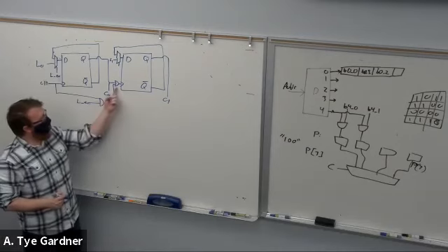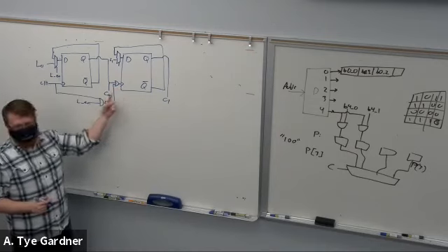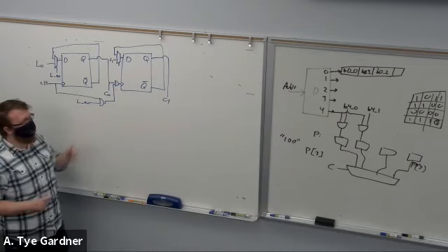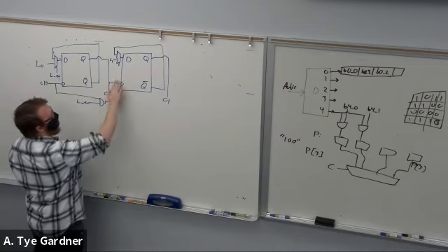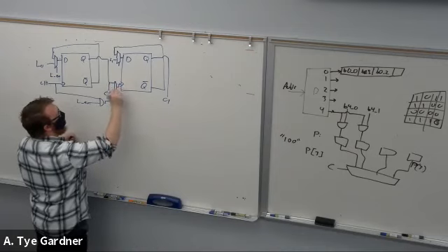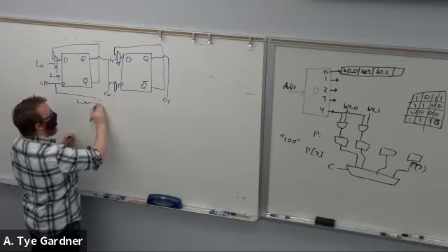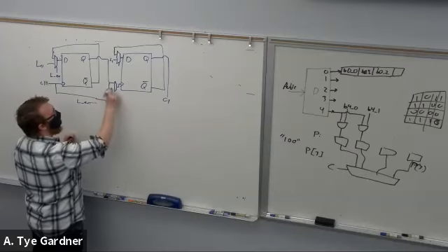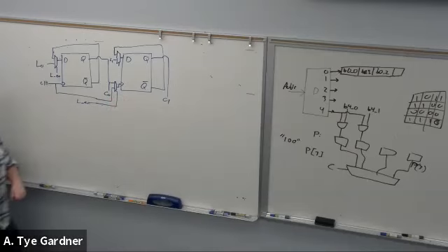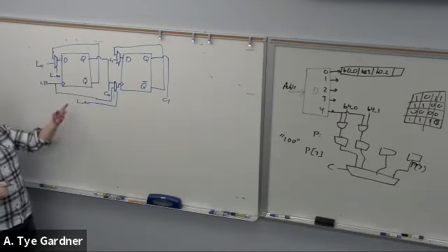And in fact, this OR gate may be better served as a mux selected by load enable. That's actually probably the better way to do it, because that way now I don't have a gated clock.